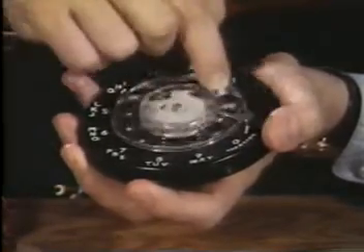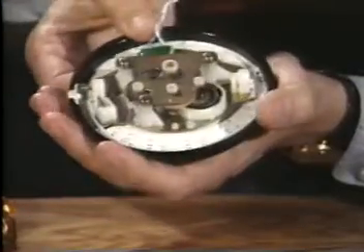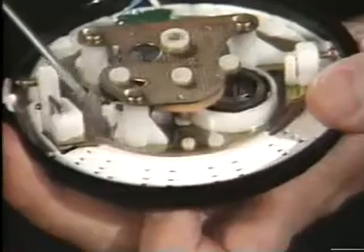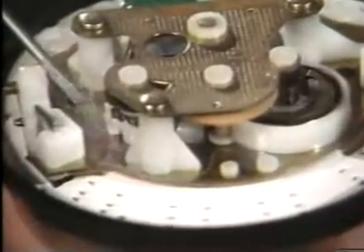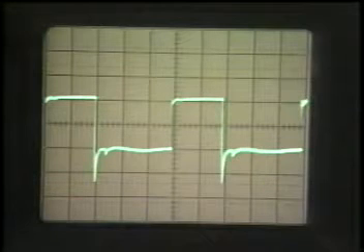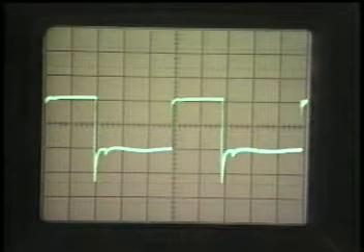During the time that the dial is returning to its original position, the electrical current supplied to the telephone is repeatedly interrupted by a small cam in the dial mechanism. Each time this occurs, a voltage spike or pulse is transmitted to the central office. 1 pulse is sent for digit 1, 2 pulses for digit 2, up to 10 pulses for digit 0.